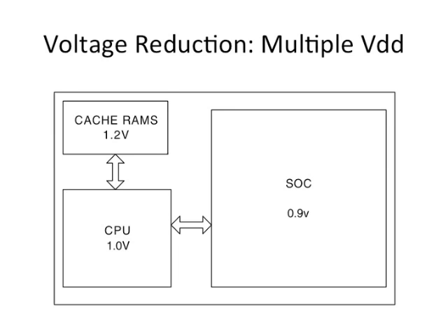Another component in that equation is supply voltage, right? Supply voltage turns out to be a very powerful knob to reduce power. One way in which this is dealt with is multiple voltage domains. When you have a chip with multiple components, you might have each of them running at different supply voltages, and this is a static setting. You decide a priori, during design time, that this is going to be at this voltage, etc., and then they run that way.